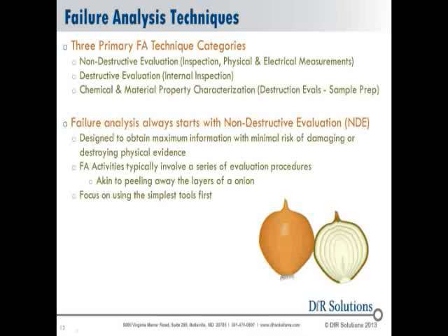And again, we always start with non-destructive techniques as much as possible, and you can consider a failure analysis very often to be akin to peeling away a layer of an onion at a time until you get to the core to see what's going on. Another good technique is to always employ your simplest, lowest cost tools first, because you never know, you might get lucky and find it using these quick, low-cost methods rather than having to go to more elaborate and costly procedures.